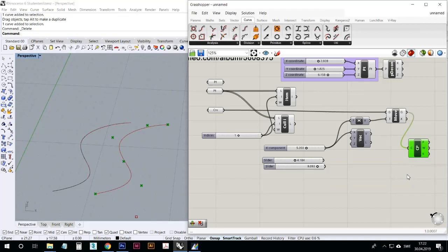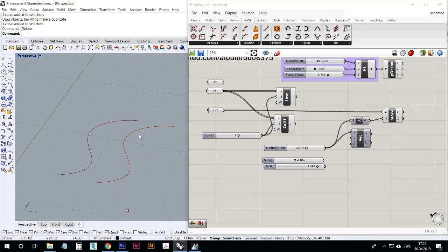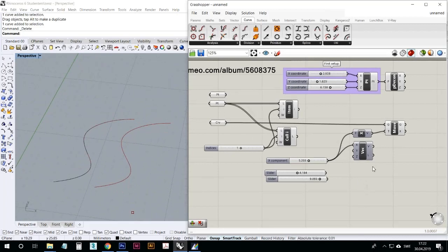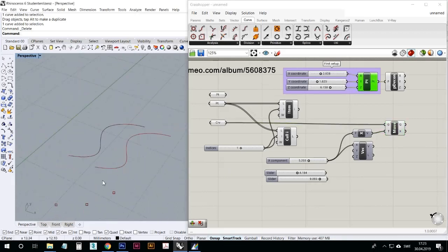You bake the sketch of what geometry you're working with. So when you work with surfaces, well, it's only a preview, right? If they are complex, they're going to look kind of strange in the preview, depending on the settings you have in Grasshopper. So it's all imaginary geometry. You have to bake them in order to use them in Rhinoceros.